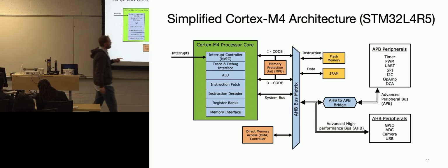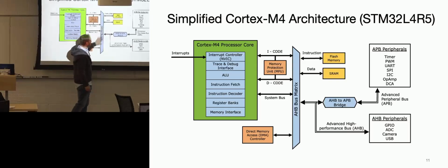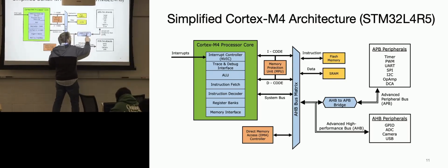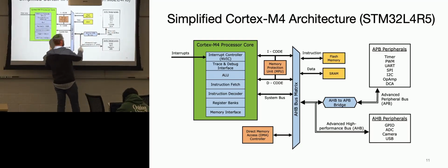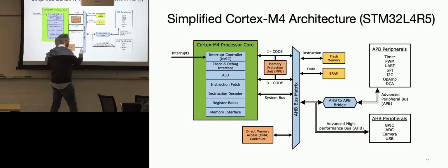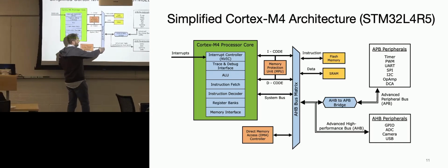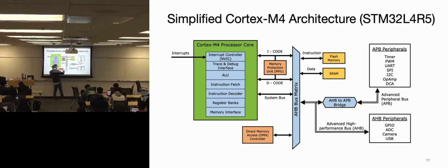What that looks like is your DMA controller is here on your high performance bus matrix, we'll talk about that in a second. And then you could be controlling information going through the advanced peripheral bus and the bridge. Remember, these are generally much slower than the advanced high performance bus, and the advanced peripheral bus is pipelined. And then this matrix is actually the idea that there are several buses. There are 6 buses for your particular device, and that means there's a road with 6 basically parallel lanes, so now you can have 6 simultaneous destination sources going at once.